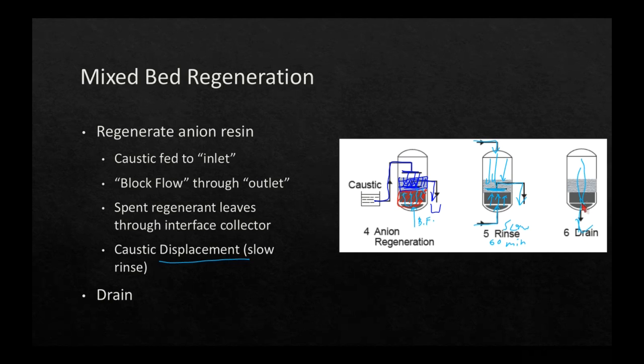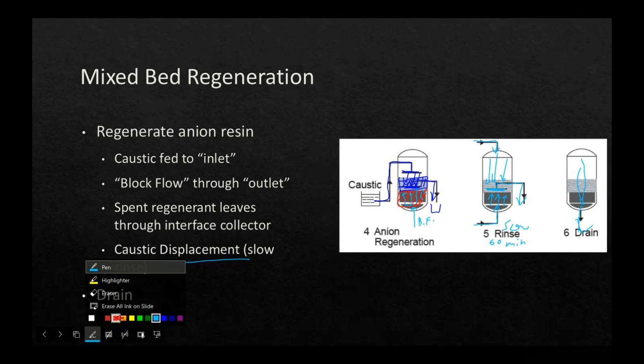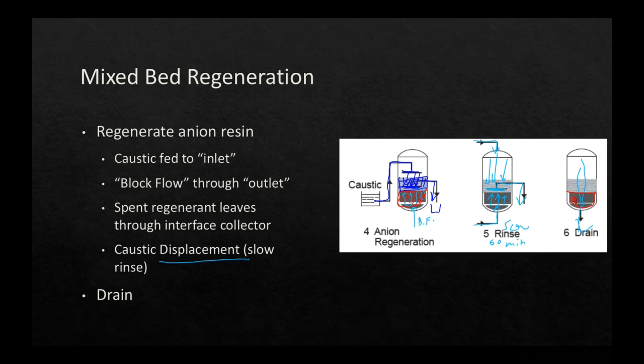Then after that, we drain the whole thing down. We drain out everything that's left in there. And son of a gun, we've screwed up. You know how we've screwed up? We've left the cation beads on the bottom, and then we left the anion beads on the top. And that's no good. That's not a mixed bed, is it? That's a segregated bed.